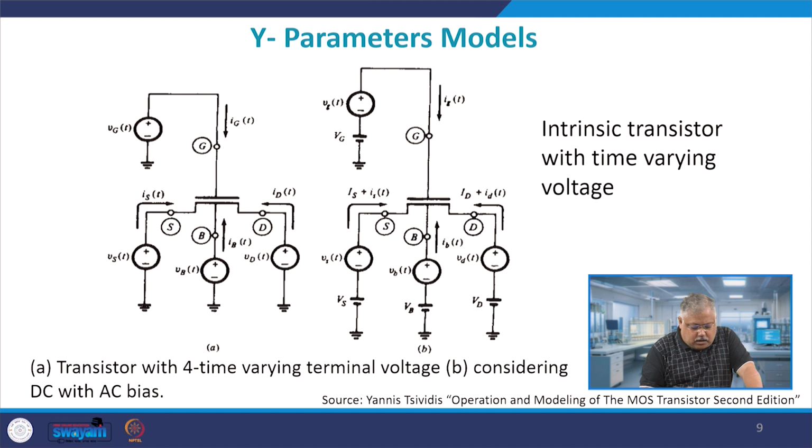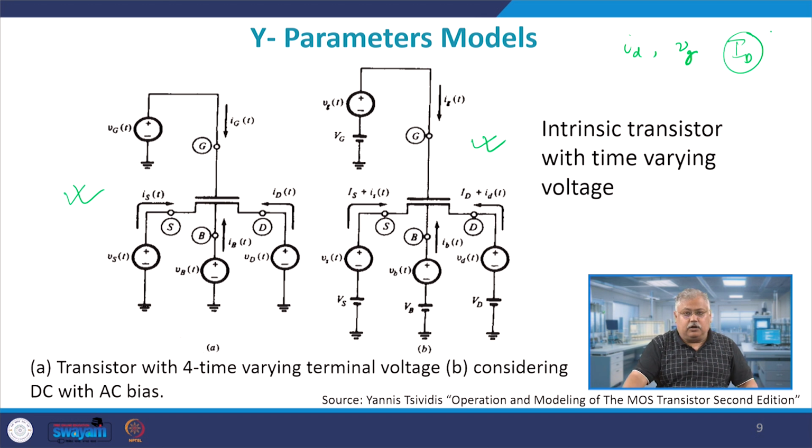If you look at the left hand side figure as well as the right hand side figure, I have applied a gate voltage here. Capital letters basically denote a bias, and when we write Vg in small letters, we mean a time varying transient response, and when we say ID in capitals, it is the DC current or voltage which you see. This methodology will be used for the next few discussions.